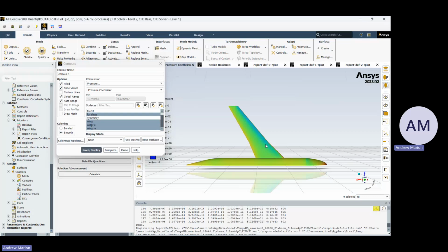It creates massive vortices. Especially because it comes from the amount of lift being produced. The higher the pressure differential, the stronger vortices you have. So larger wings will produce larger vortices. And so when a 747 lands on a runway, they can't land a Cessna right after because those vortices stay there for a while and will affect the plane. It might even flip the plane or throw it off.